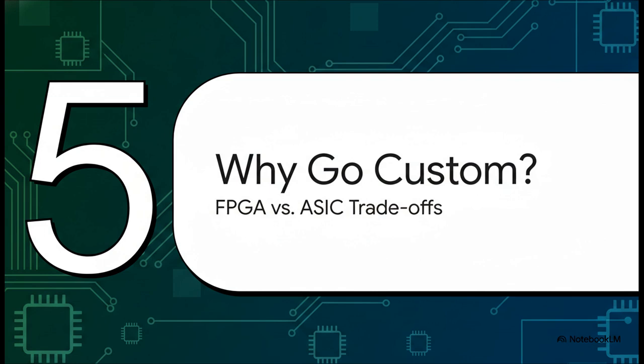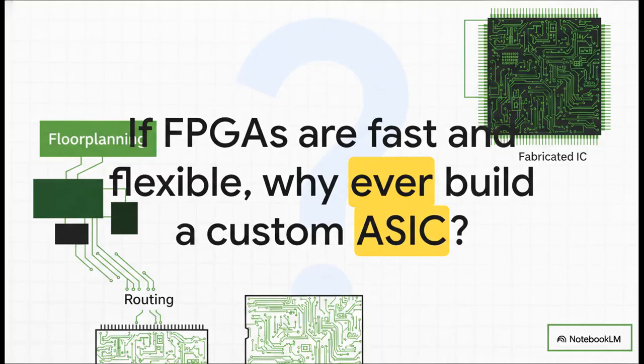So all of this brings up a really crucial question, one that pretty much every hardware designer has to ask themselves at the start of a new project. I mean, think about it. If FPGAs are so flexible, and you can reprogram them, and they're way faster to get up and running, why would anyone ever go through the expensive, time-consuming, and totally permanent process of making a custom ASIC? Well, the answer comes down to performance and cost, but with a huge asterisk, only at massive, massive scale.